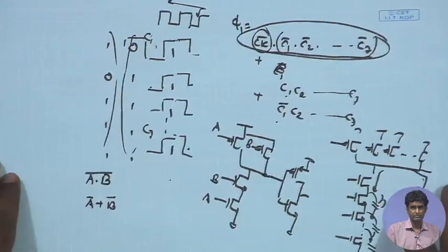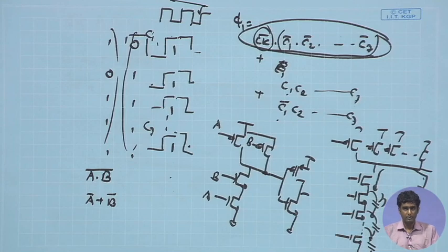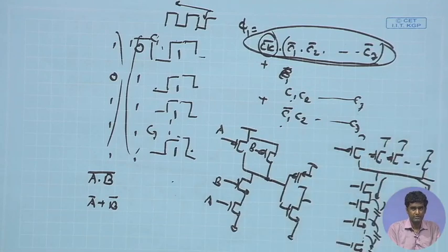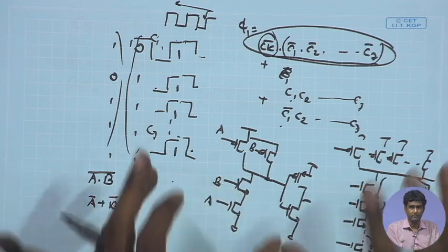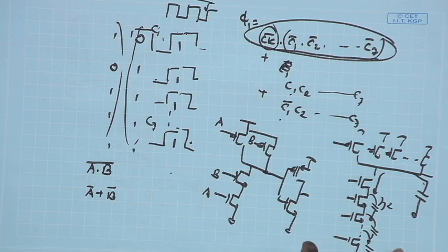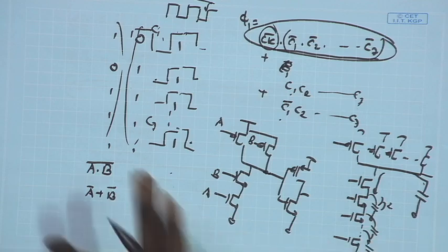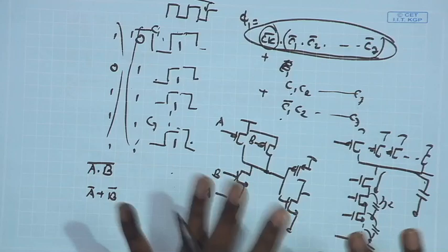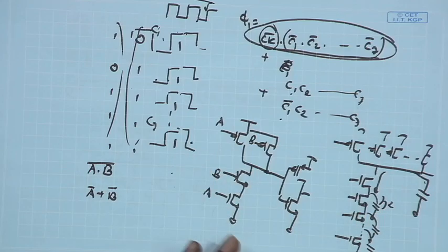Any question before we end this discussion? So, we have covered the building blocks of our ADC in sufficient detail, starting from the ramping circuitry, comparators, their non-idealities, sampling circuitry, along with the comparator design, its specifications, its non-idealities, including offset cancellation, and finally, we also came into the digital controller part, where although the control is simple, we dealt with the constituent elements at block level, the overall functionality of the control operation, how the pulses are getting generated, and finally, we went into the transistor level implementation of all those digital blocks, looking into the important definitions and issues at transistor level implementation of those digital components. So, this completes the overall controller module that we have for the A to D converter.